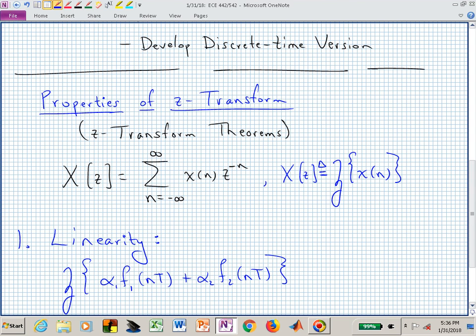So now the question was, a lot of times when you're doing the Laplace, we're integrating from t equals 0 to infinity. Here I'm saying let's just define this Z transform more generally and go from minus infinity. So it would be like taking the Laplace transform from t equal minus infinity to infinity. You're most familiar with the one-sided Laplace. We will do a lot of one-sided Z transform where the lower limit will actually be 0. But if somebody starts asking you questions and you look at them like, I've never seen a two-sided Z transform, they might wonder where you learned your Z transform.